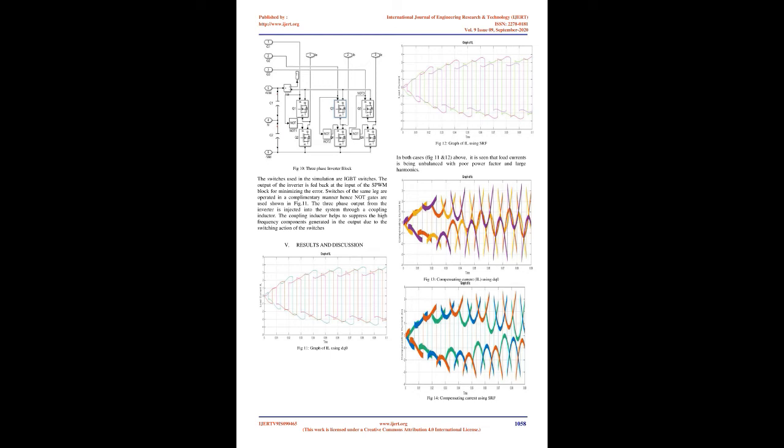In this control approach, the conventional controllers are replaced by the fuzzy controller, which possesses two inputs and one output signal. The error, E, and its derivative, DE, are used as the inputs to the fuzzy controller, while the output is the command, CDE. The intelligent current control methods do not require a model of the SAPF, but they need precise knowledge about the operation and behavior of SAPF systems. [10] carried out a comprehensive analysis of current controllers.